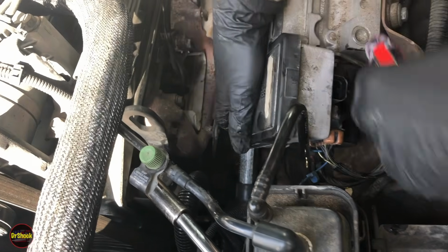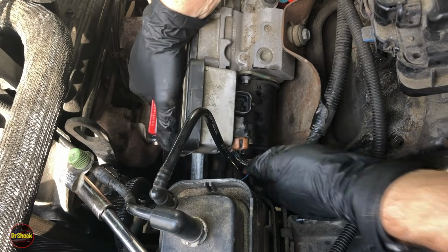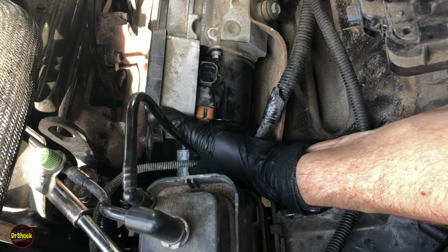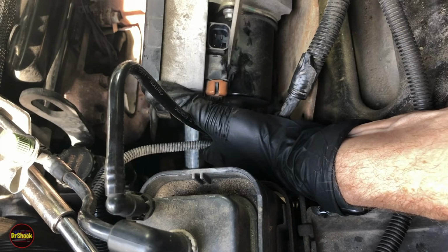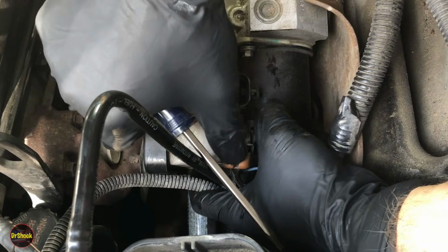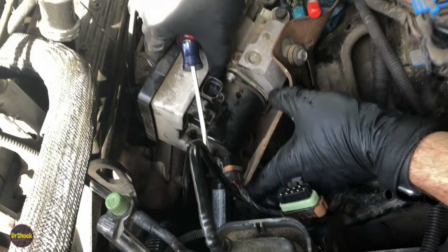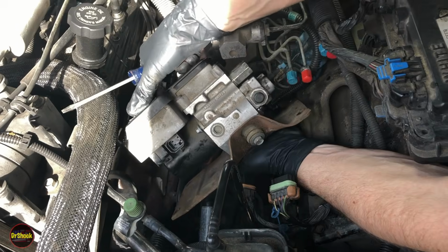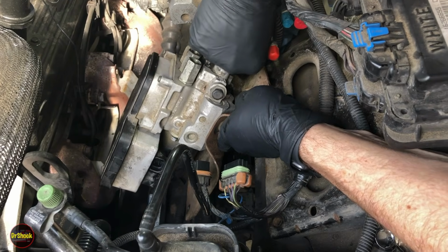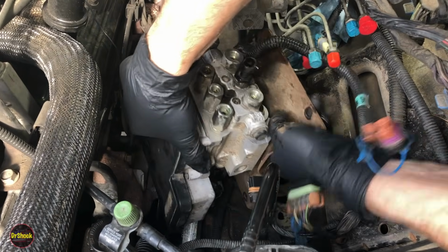See, what we're trying to do is get our hand under the pump here. And see, that's the connector's retaining clip right there. And that's the guy we want to have wedged up a little bit while we pull back. Now we got it off. All right. Now it's still held on by one more thing. So we're just going to kind of rotate it around. We got to get, or two more things rather. We got to get the pressure switch to let go. And then we've got a little harness clip over here.